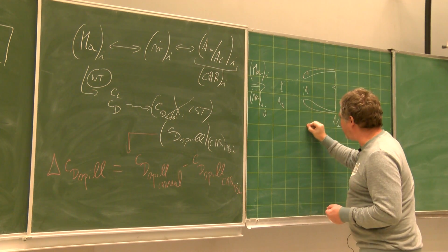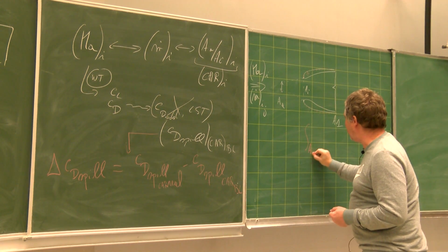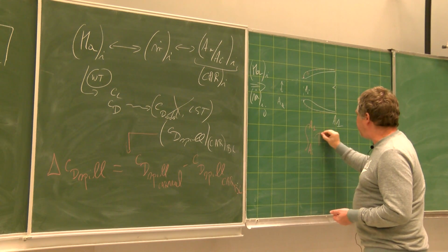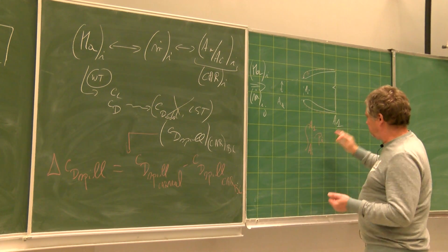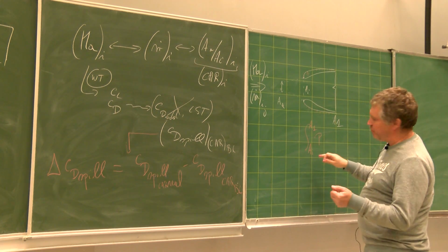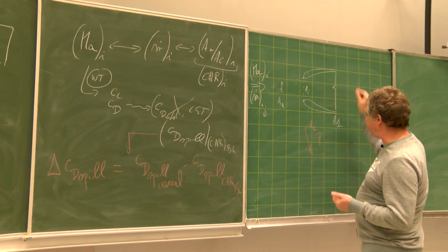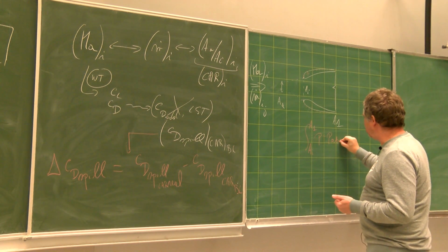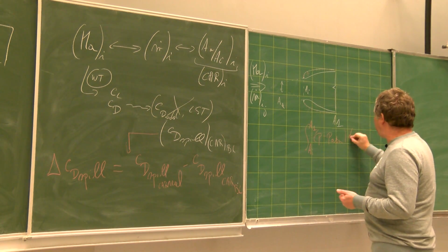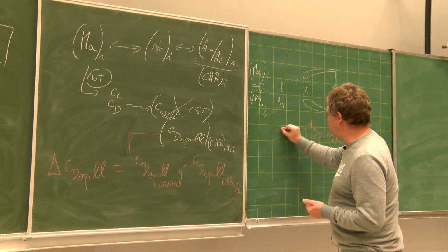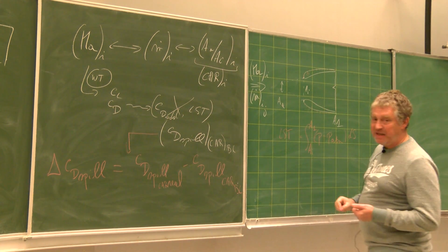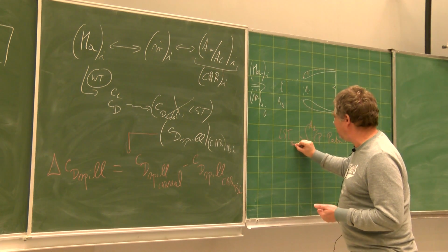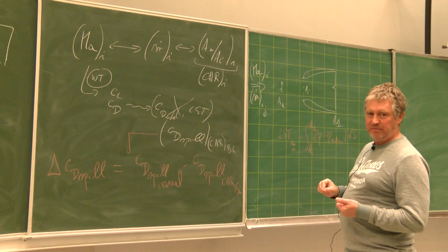They will integrate between the section AI and the section A1 the P, because I is also this one, the P that they have in different places, minus P atmospheric, multiplied by ds. Like this, they will obtain the LST, the lip suction thrust, for the different Mach numbers and the different m dot.